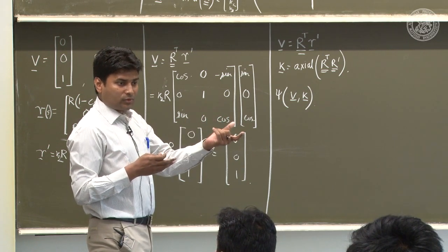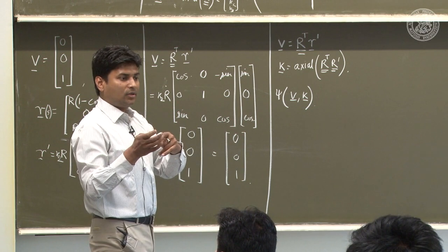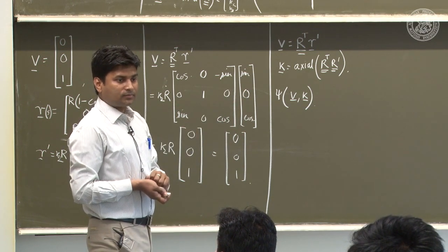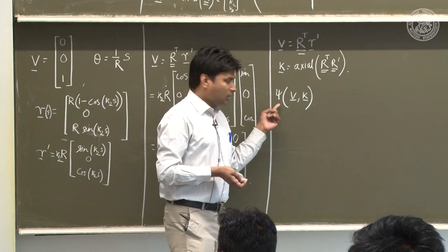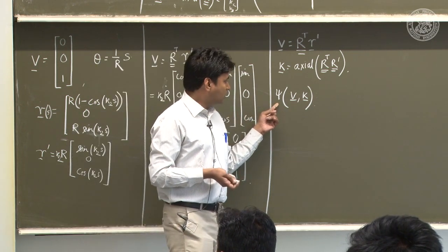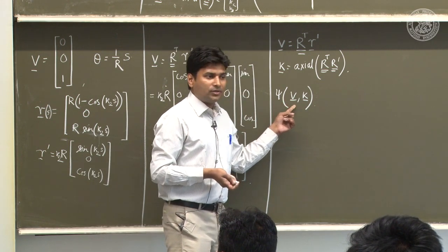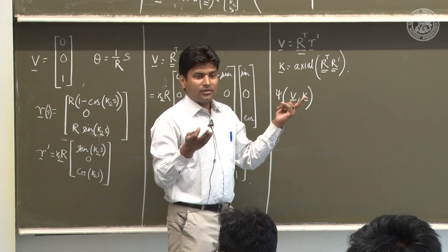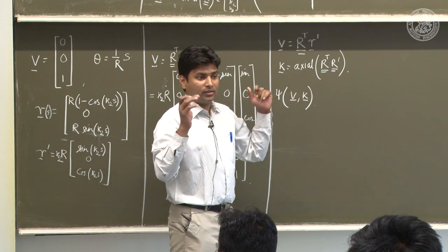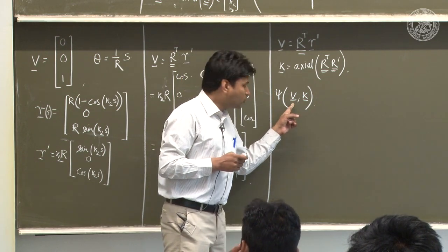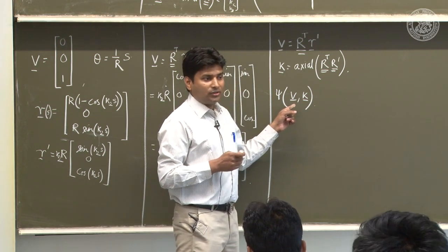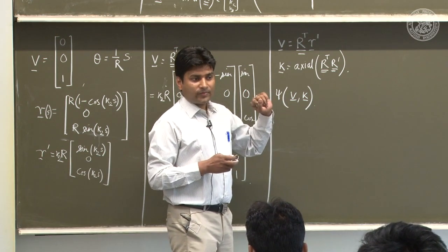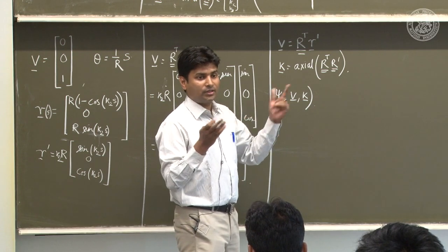So you take the derivative of stored energy with respect to any strain measure, you get the conjugate stress. So here also, if I take the derivative of strain energy with respect to these strain measures, I should get some conjugate stress resultants, because these are not the usual 3D strain quantities. So these are some resultant strains, so I should get some resultant stress.